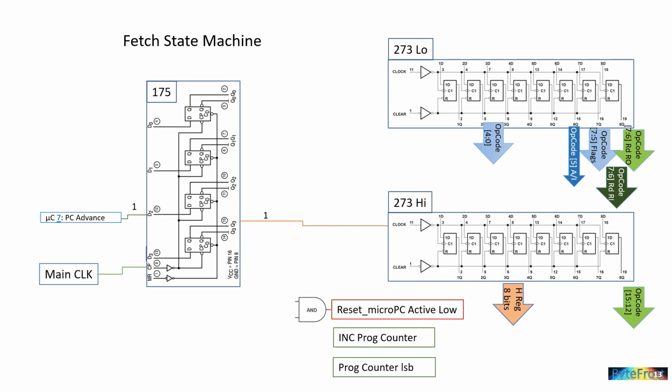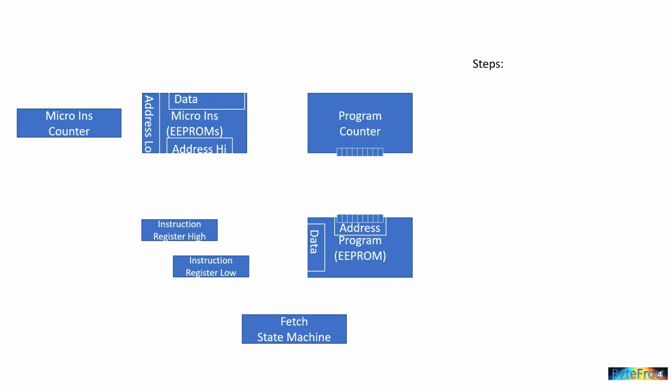Now, you might have noticed that we seem to have a fundamental problem. If every instruction loads the next instruction by sending a PC advanced signal when it finishes executing, how do we load the first instruction in our program? Our state diagram has become a chicken and egg dilemma, as it can't get itself started.